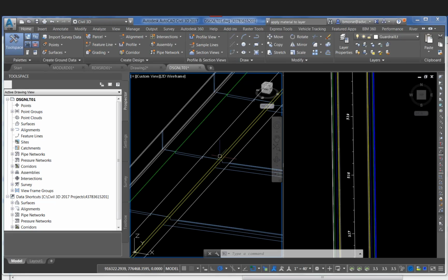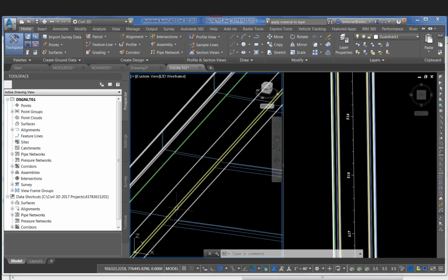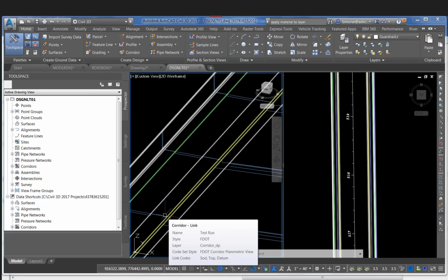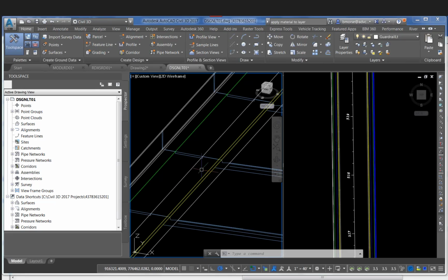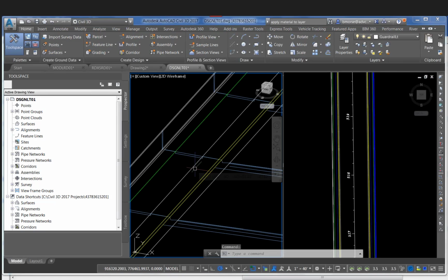Now we're talking about corridor section sampling, not the cross-section view sample line group. This is just the sampling interval baked into the frequency of your corridor model. So you can see that you've got your shape for the curbing here, and then you get your lane line. Okay, and then there's a sidewalk, and then there's some railing on that particular side of the road there.